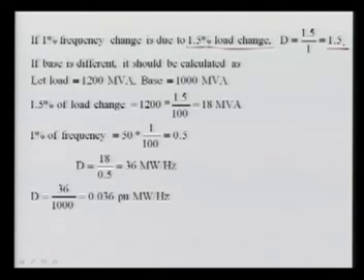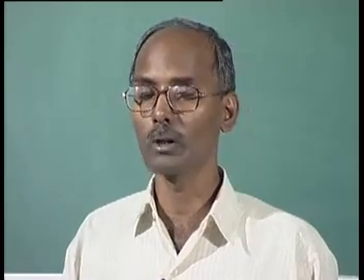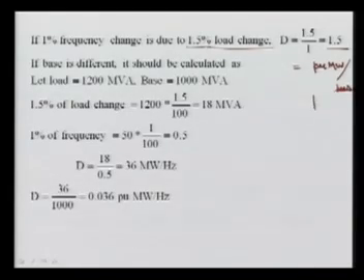Now the question, what is 1.5? Here we are talking about percentage, so it is in per unit megawatt over per unit hertz. So for a given base power and nominal or rated frequency, we can calculate the value of D in actual quantity, that is megawatt per hertz.